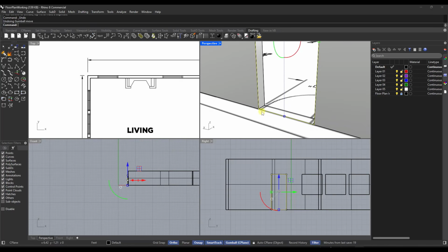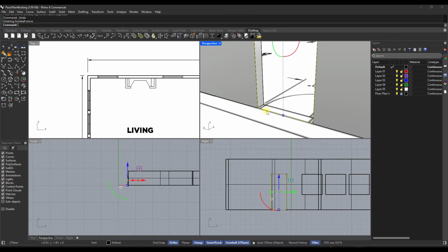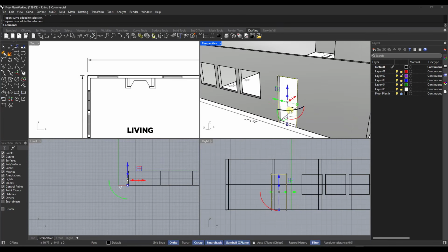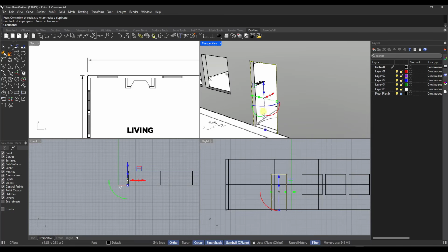And so to model out our frame, what we're going to do is remove this bottom edge. To do that, you can use the function delete sub curve. And what that's going to do is allow us to pick a point on this line. So we're going to click right here, we're going to click right here, and that's going to remove the bottom edge of our curve. So now if you look at this, notice how this is basically a 3-sided box right here.